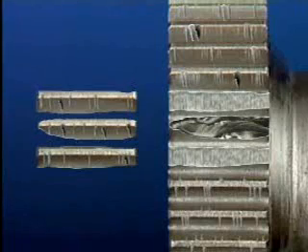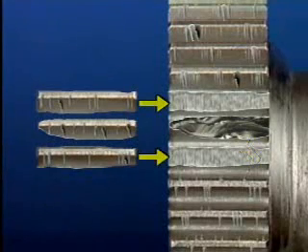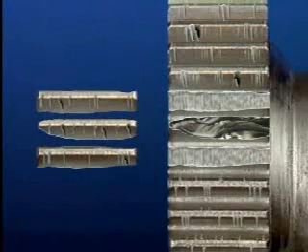There isn't much that you can do about breaks caused by internal overloads other than replacing the damaged gears. However, when you discover a failure that was caused by an external overload, you'll have to investigate the problem further. A first look at this damaged gear shows that a tooth was broken due to fatigue failure, and that the adjoining teeth broke due to overload. It looks very similar to the gear that failed from an internal overload.